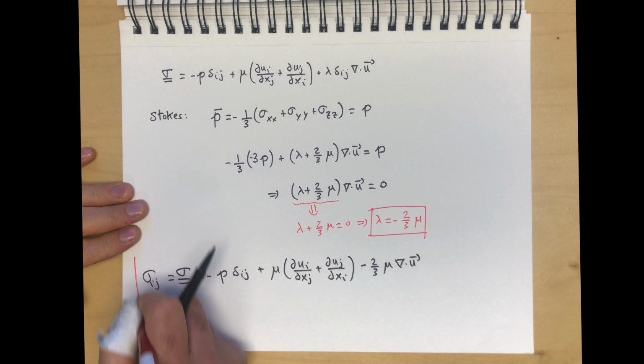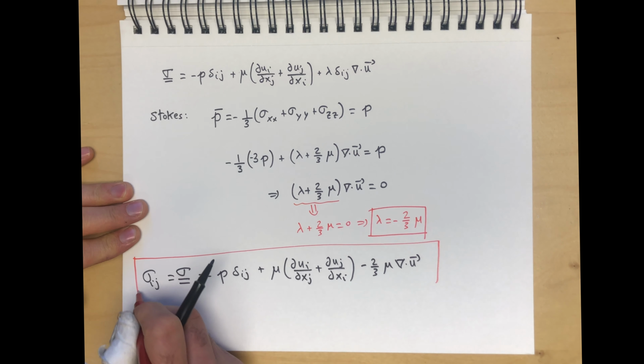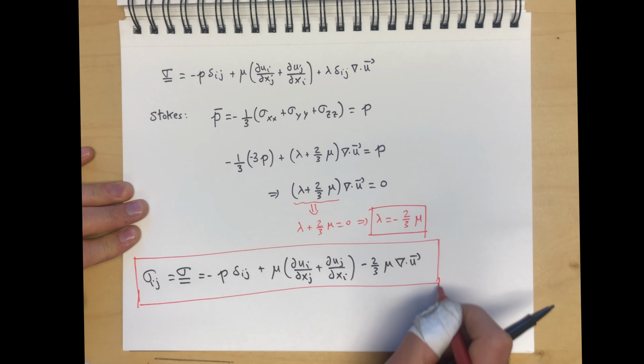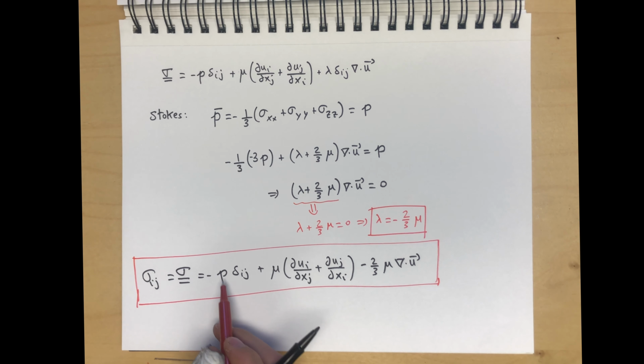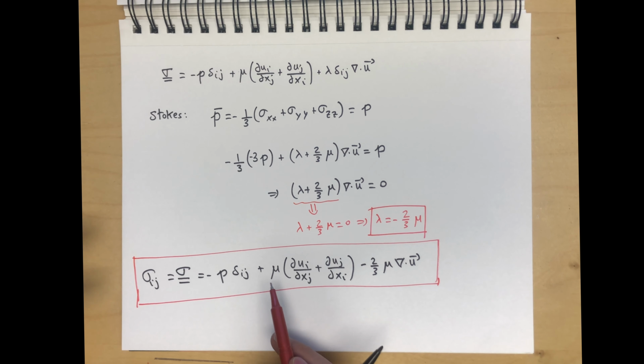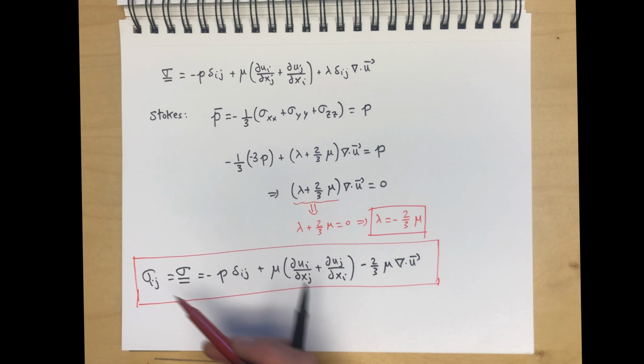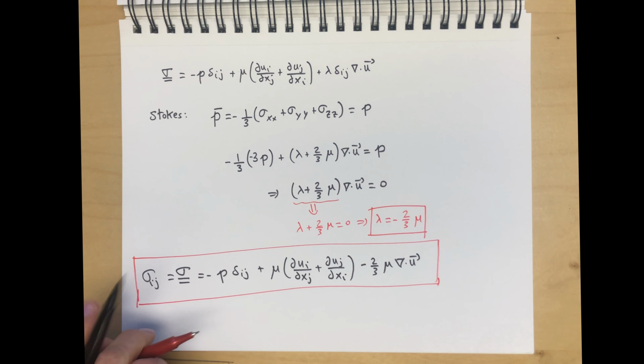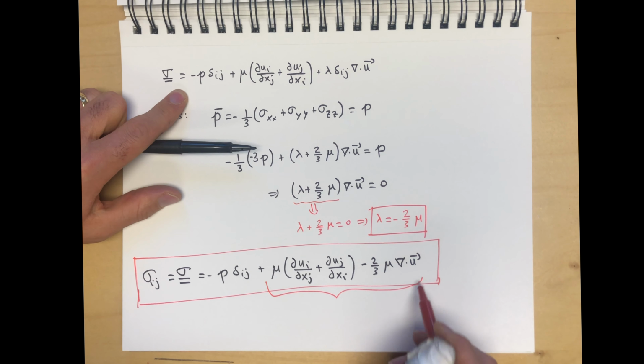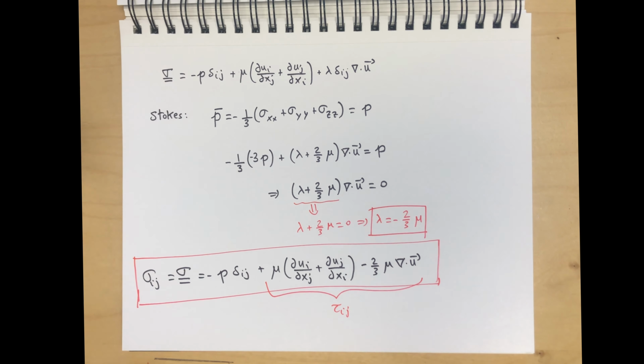That's the most general form of the full stress tensor. This includes the pressure, so obviously when you put this form into the governing equations, you should remove the pressure gradient or simply use tau, right? So choose this thing as tau ij if you're explicitly including the pressure into your governing equations.